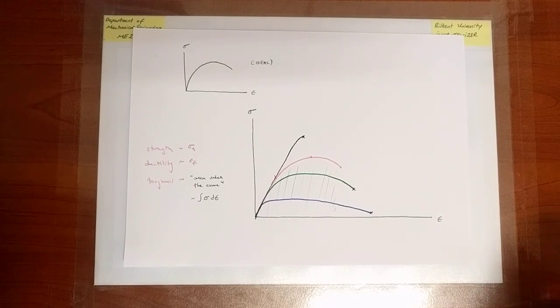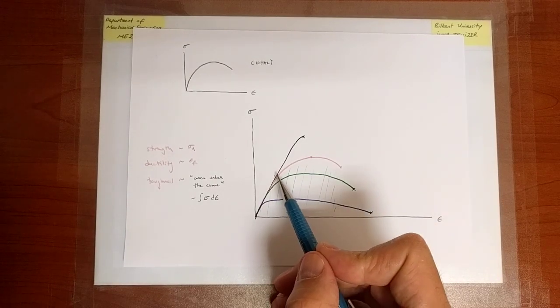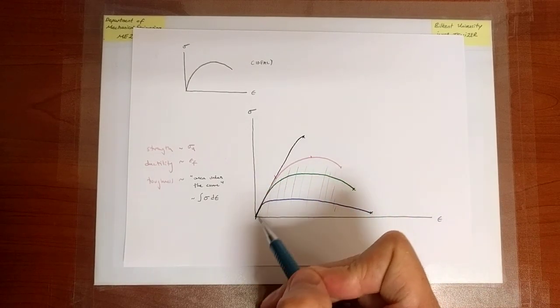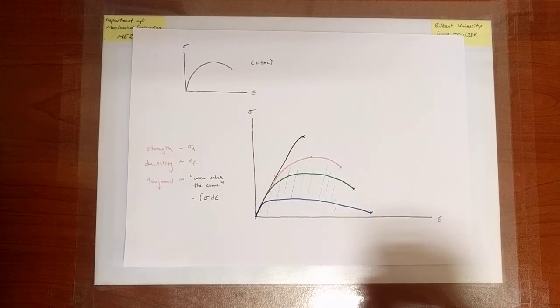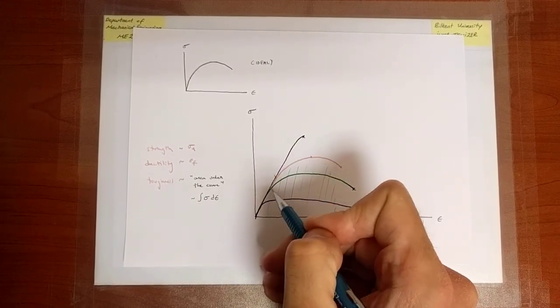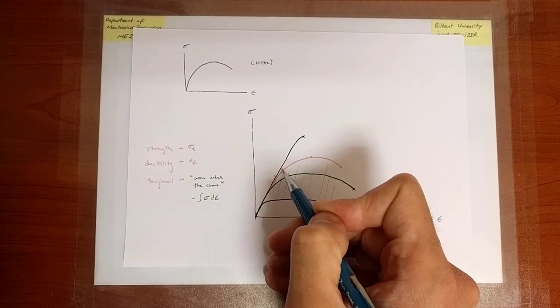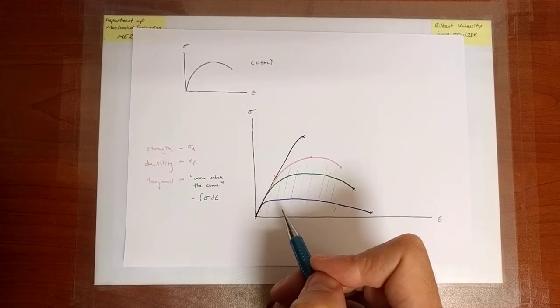And you're adding small amounts of different materials to make that iron become steel and behave in drastically different manners after you also perhaps treat it in different ways. But because the underlying material is the same, and that's the large portion of the steel alloy, it's iron, the curve in the elastic portion has a similar slope for all types of steel alloys.